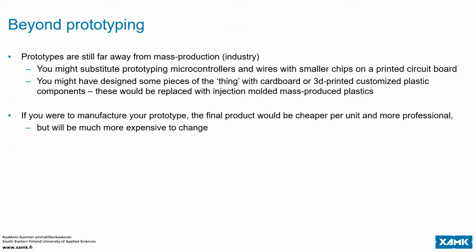Prototypes are very far away from mass production or industry. You might need to substitute some of the prototyping tools, microcontrollers or single board computers and wires with smaller chips or printed circuit boards. You might have designed some pieces of the smart thing with less than flexible and durable materials like cardboard or 3D printed custom plastic components. Those would be replaced with injection molded mass-produced plastics.